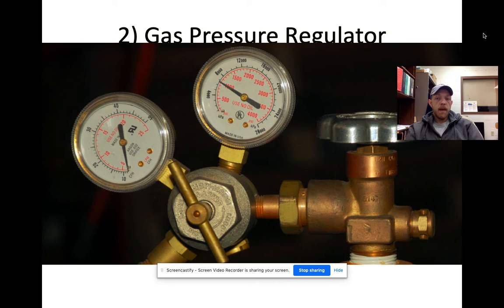Another reason there could be a malfunction is in this pressure regulator. I have seen sometimes these gauges, for whatever reason, are compromised and the gas starts to actually shoot out. There's just a small little valve in here that reads the pressure of gas, and things wear out, they deteriorate. So when you turn that gas on, if the valve stem in these gauges is compromised, these face plates and these covers can become a projectile. So you always want to stand on the opposite side of the regulator.